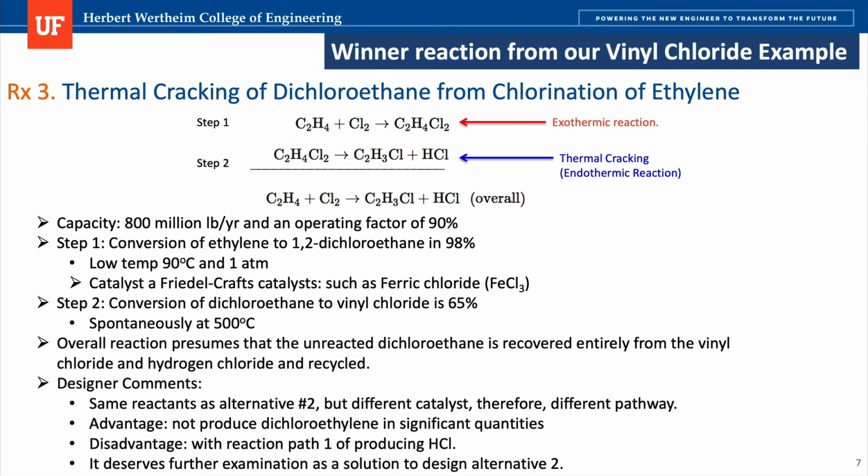In one reactor, you can have side reactions, so that will happen in the same reactor. So you need to understand the conversion, the selectivity, and all that for your particular reaction. Then you need to have information that you can get in the literature. Maybe you have information about which components are in excess. You may have information about the residence time, or the volume of the reactor. Either of that information is important, especially when you do sizing later. Then you summarize the designer comments just to remind yourself of the important aspects of this chemical reaction.